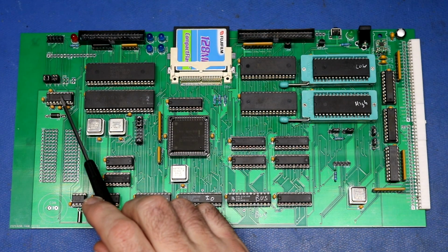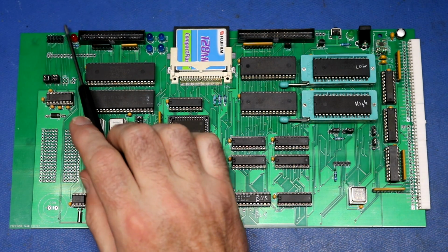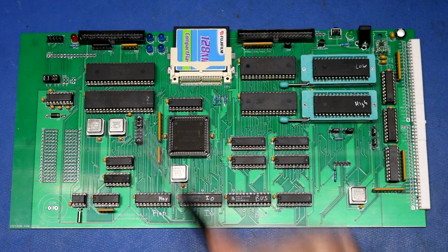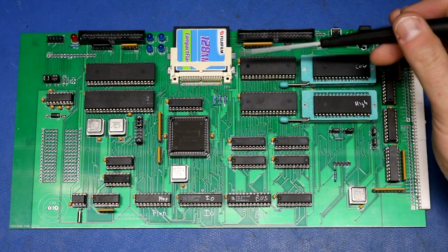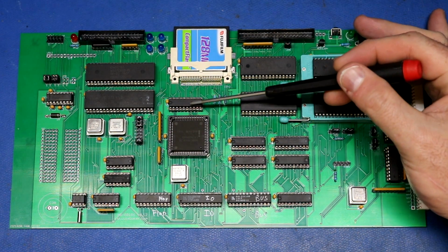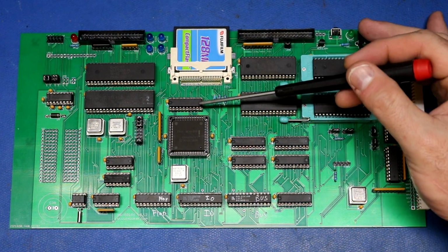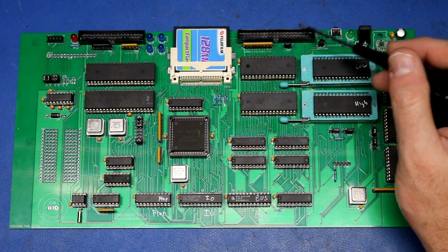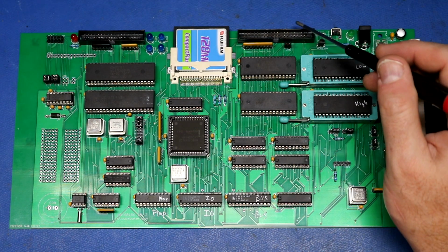Max 202 driver for the serial port, coming up here connecting with your serial header. The header here would be for the floppy, standard 34 pin. We've got our compact flash device here and an 8-bit I/O buffer for it. We operate the compact flash in 8-bit mode, and those lines are also plumbed out here to this socket in case you want to plug in a 40-pin DOM module.